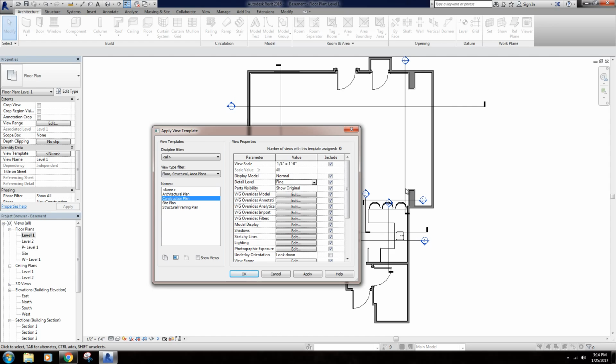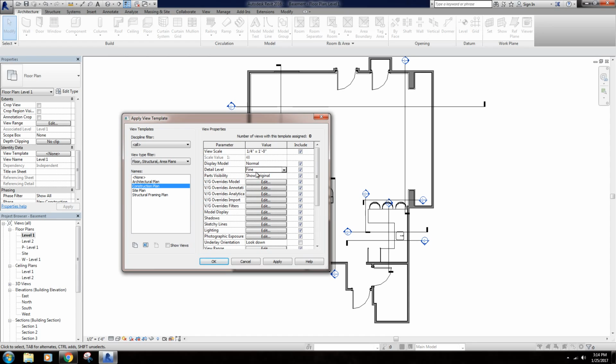So around these, it'll show the stone, the cement backer, and then the stud makeup and that sort of stuff. So I tend to like to keep stuff on fine, but when you get into a site plan and that sort of stuff, a lot of times it might be nice to throw those on coarse, so you're getting just a general overview of how the plan's working.